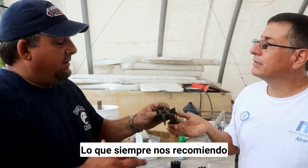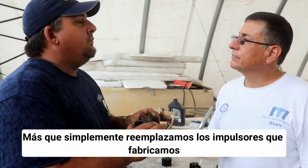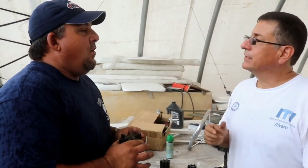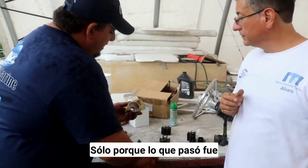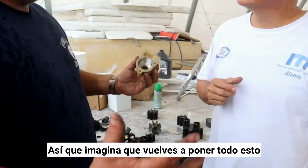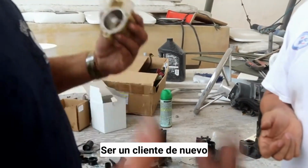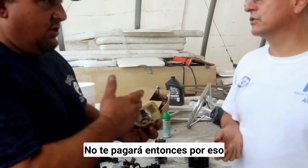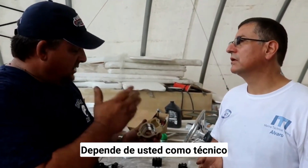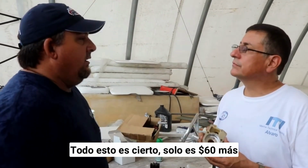What I always recommend to our customers is we don't replace just the impeller. We make them replace the whole water pump, because you don't know if there's a hairline crack in the housing. Imagine you put this all back together, you didn't see the crack, and you had to do it all over again. The customer's not going to pay you. So it's up to you as a technician to change out all the parts. It's only about $60 more for the whole kit.